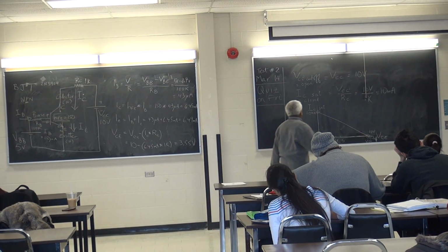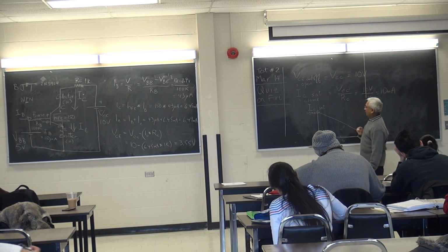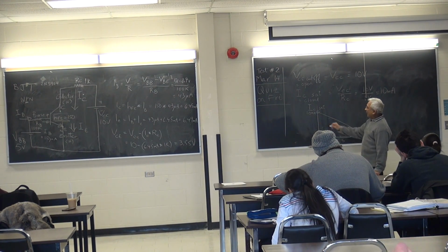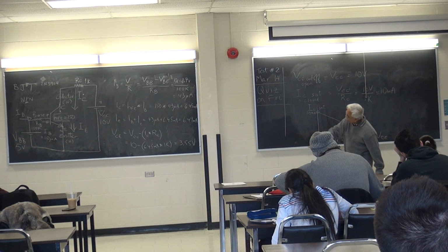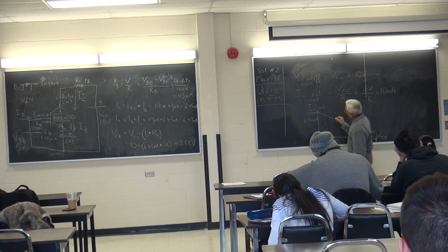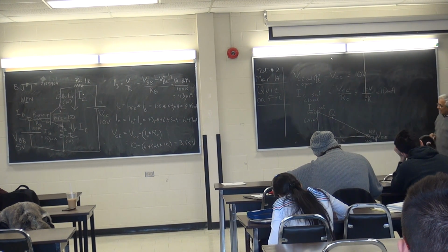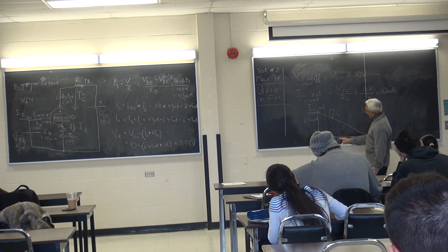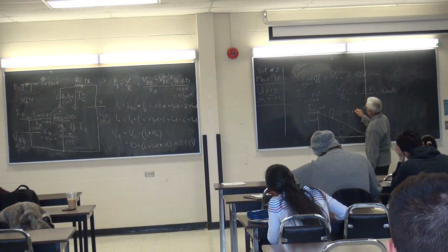And then what I do is I take this point and go up and hit the line and then go across. And that is my IC value of 6.45 milliamps. At this point, I call it the Q point. And I indicate that as a coordinate of X and Y values. The X value is 3.55 volts. The Y value is 6.45 milliamps.